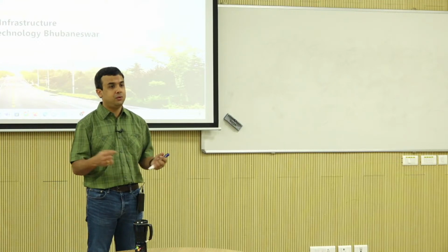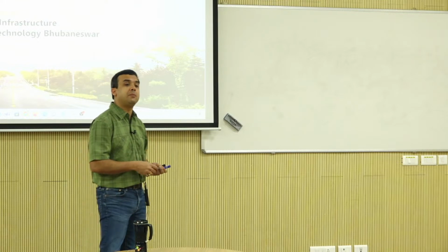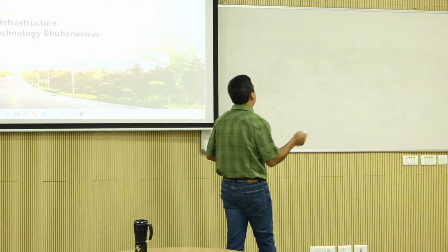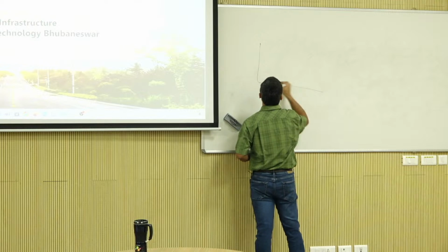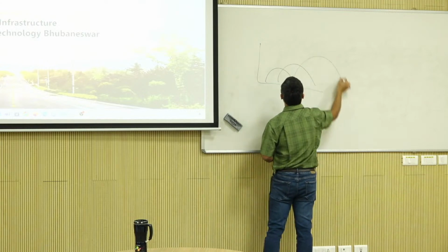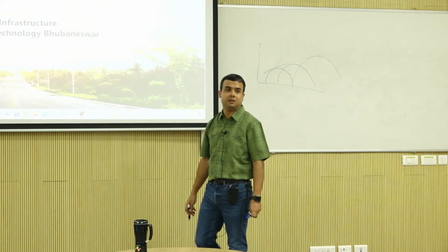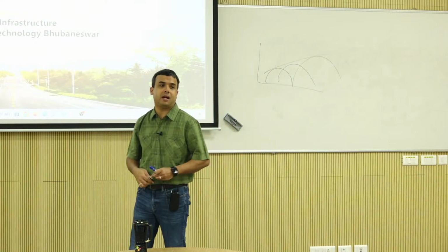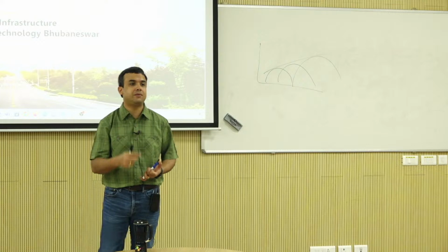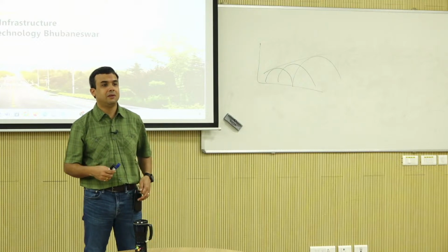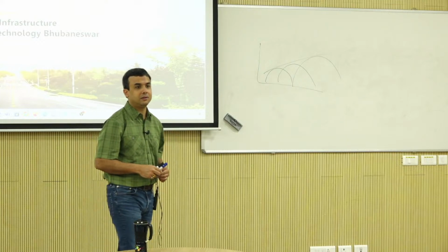If you have seen resilient modulus, but if you do a triaxial and you are able to plot a Mohr-Coulomb envelope like this, then it answers everything. Then it's a frictional material for sure. Try that. Try 3 different confining pressures, at least 2 different confining pressures. Do you see a difference in shear strength? That will work.